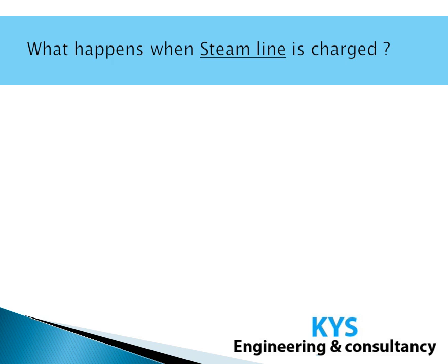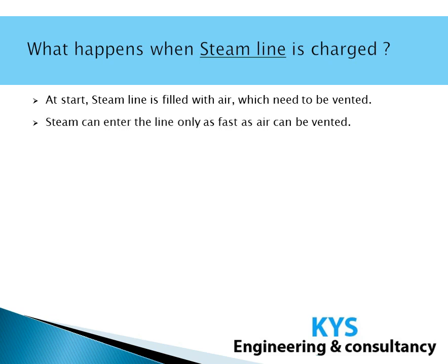Let us see what happens when a steam line is charged. At a startup, the steam line is filled with air and some non-condensable gases. This air and these gases need to be vented. Steam can enter the line only as fast as air can be vented.